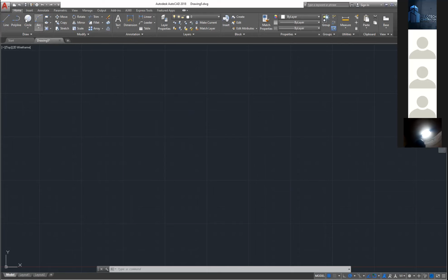It doesn't end there. Again, these have been put like this because these are the most commonly used commands under draw, okay? If I hover over this draw and click on this drop down arrow, you'll see that you have more commands here, okay? These are more commands which you can still use under draw. And you come here again, you see you still have more commands. These are still useful, but of course you rarely use them. But if you need to use them, this is how you access them, okay? But these are the ones that you are going to be using very often. So to go back up, you click on the draw again, and it collapses the list.